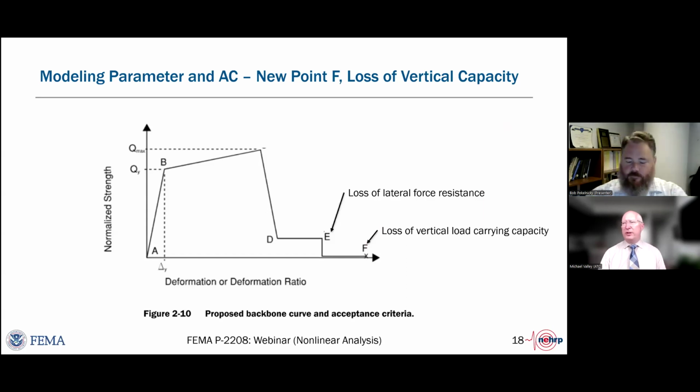I think I have one more here. The drift limit of 6%, does that apply to all structure types, steel and concrete, for instance? Yes. Okay. And so maybe a question for me, is there any guidance given for methods to investigate that limit or extend that limit? This is where the change in ASCE 41-23 came. There was some more commentary given and an explicit qualifier added to the standard's text saying that if you can justify stability and model performance at greater than 6%, that is not an unacceptable response. Okay. Very good.